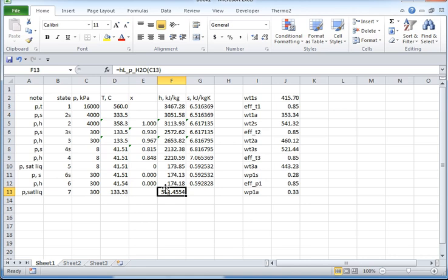that feed water heater. Okay, how about, well, I don't need a 7S or anything like that. State 8, though, I have 8S going through the pump and 8 actual coming out of the pump, right? So we have pressure, entropy, pressure, enthalpy as my notes. It comes out at what pressure?